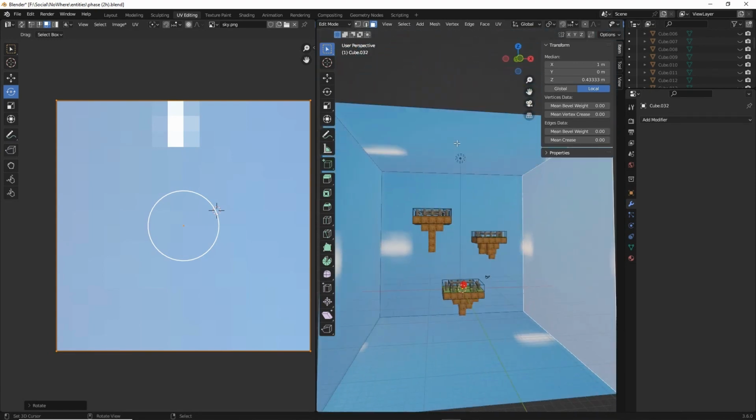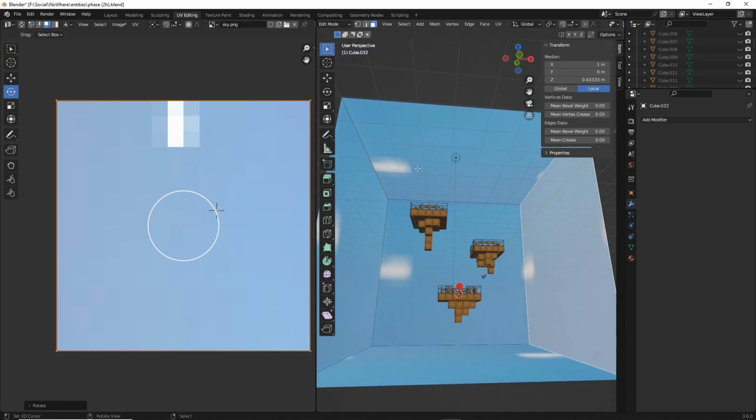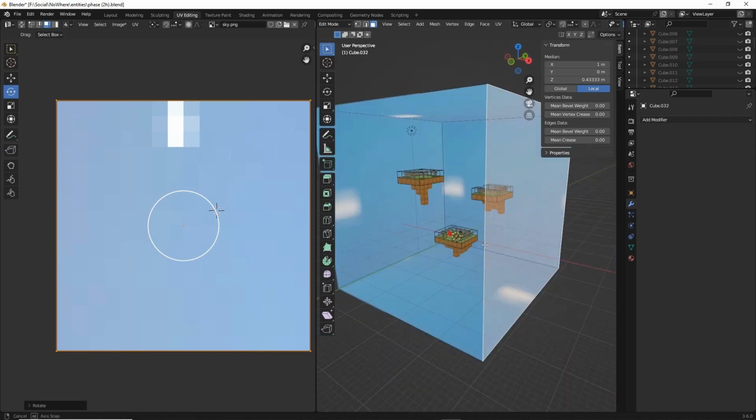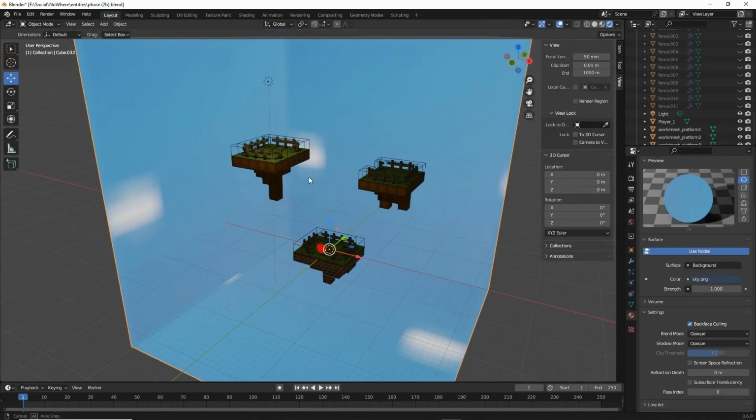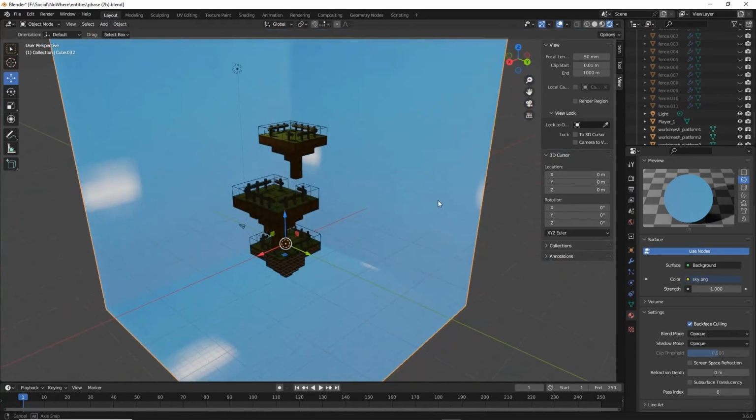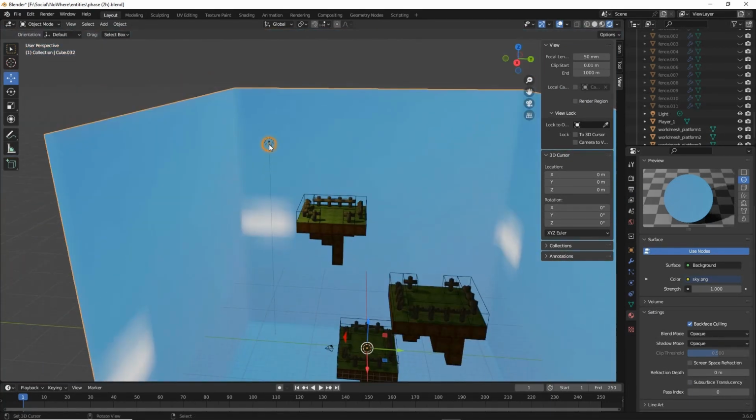And of course the top and bottom faces present a bit of an issue because we can't rotate that in any particular direction that will solve this color variance. So when we're doing skies or textures that are going to be used as backgrounds, we have to be aware of any color variance that can be compensated for by rotating UVs on the vertical but not necessarily on the horizontal. So that is a quick fix, and it gives us our skybox. Let's change the color of the light.